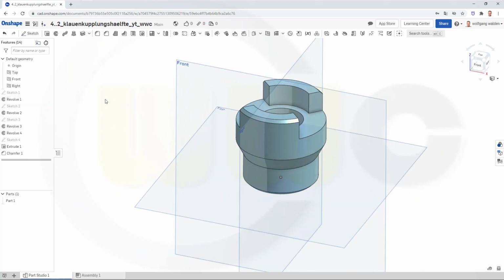Great. In order to use the hole tool, I need a sketch. So I need a plane, and I want to do it in a similar way. So I will do a plane tangent to this one or with a distance to that one, and there we'll do a sketch with just the point. So let's take a look what kind of planes can we create.